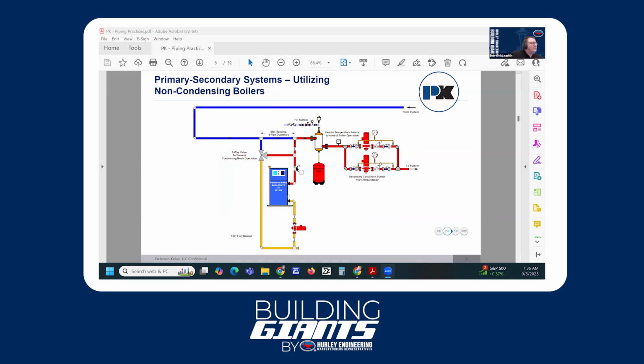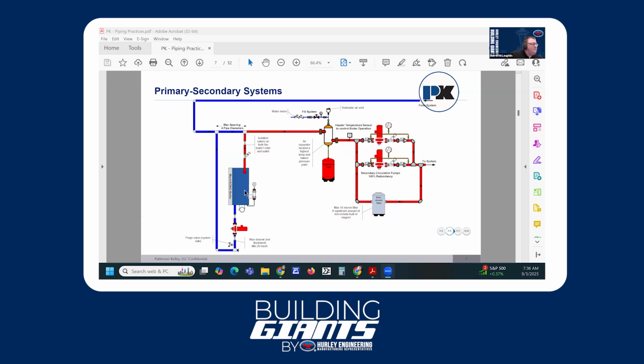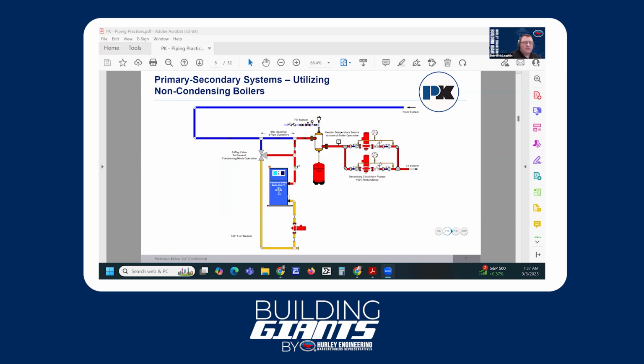So one thing to keep in mind is when we're running this system here, we've got a non-condensing boiler. We can run this at any temperature available to that boiler. So we can run a 100-degree set point. We can run a 180-degree set point. Now, ideally, we'd rather be below 140, or at least keep our exhaust gases below the dew point so we're condensing. That's where we'd like to be. But if we have a non-condensing boiler, like is shown in this slide, now that temperature range of set points is not available to us.